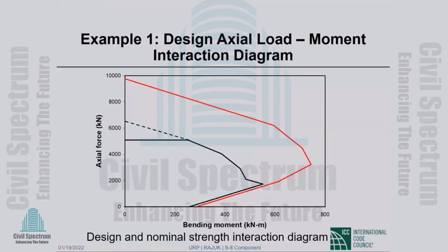But if there is a horizontal crack in a column, that is not caused by rusting. That has deeper and bigger problems. If it is only spalling, it is one matter. If there is really a horizontal crack in your column, you better figure out what is going on. I wouldn't seek to calculate remaining column capacity.